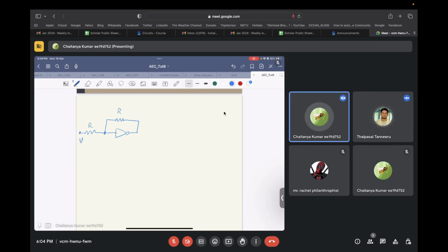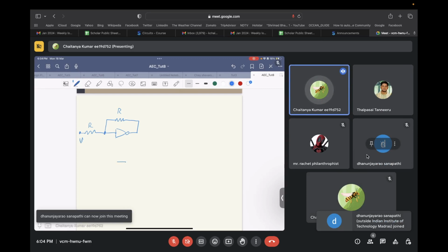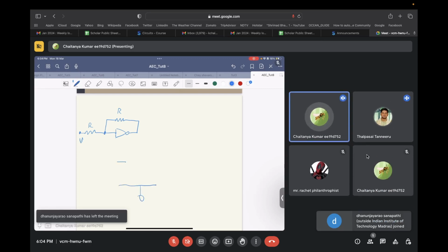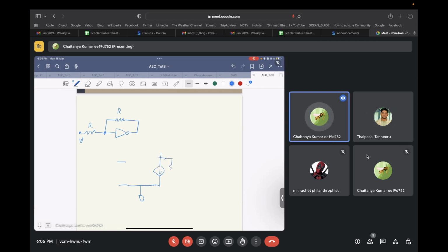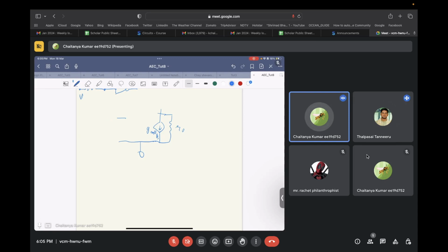One thing that you can see is that every inverter is basically what? Instead of making that complicated small signal model like this, you have this model, which might be a little inconvenient to write and to work with. So what you can use, as we discussed last time, is to model this as a transconductor with a transconductance value. So it is a bubble transconductor.